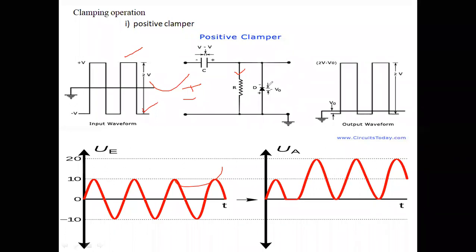Here the diode will be on. In the sinusoidal case, when the input signal reaches 0, at this time the capacitor charges back, and it maintains the constant voltage. When it is short circuited the time constant is 0, therefore it charges quickly. When it is off, we are maintaining a large time constant, R into C. R into C is a large time constant, therefore it discharges slowly.